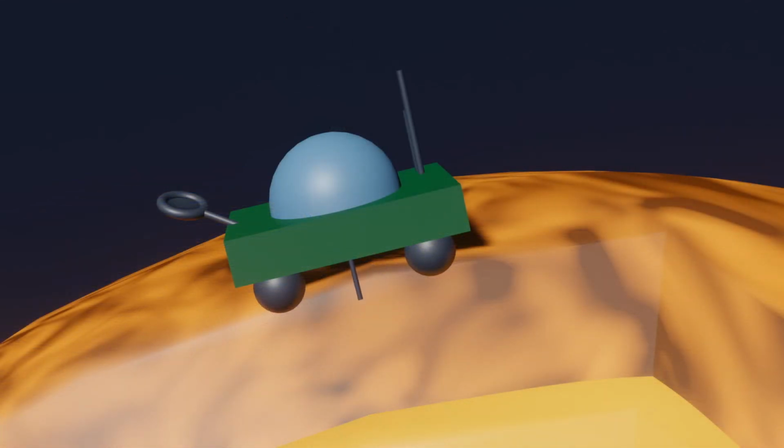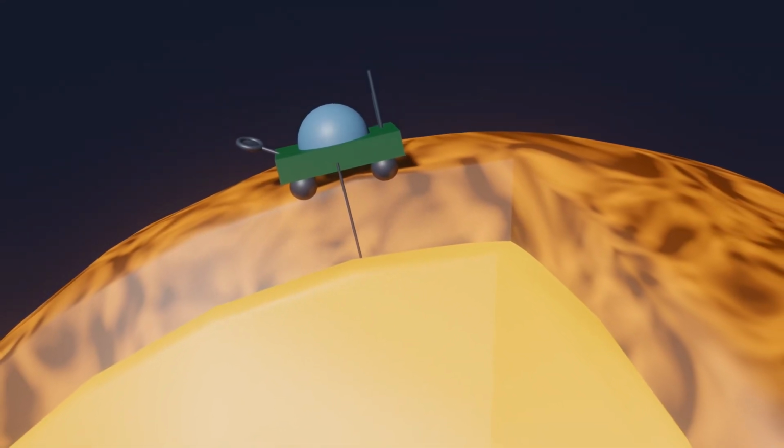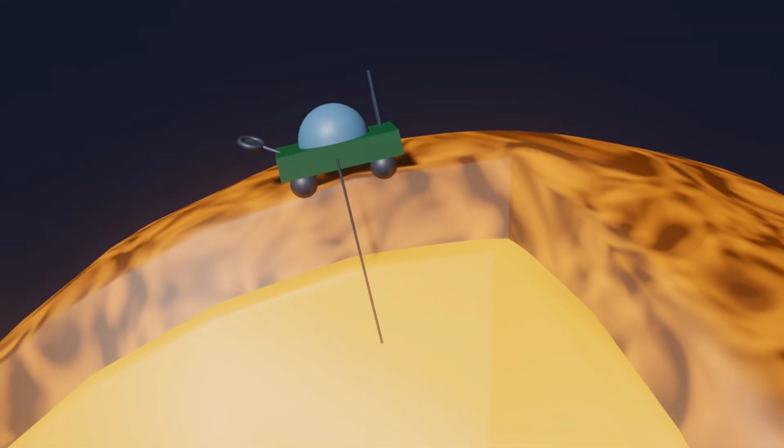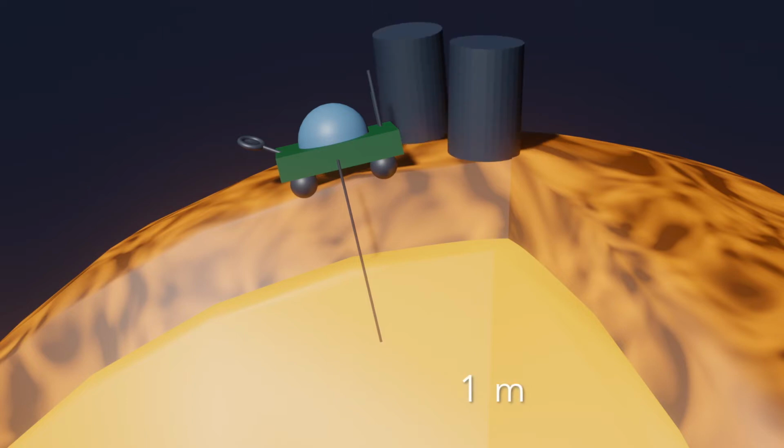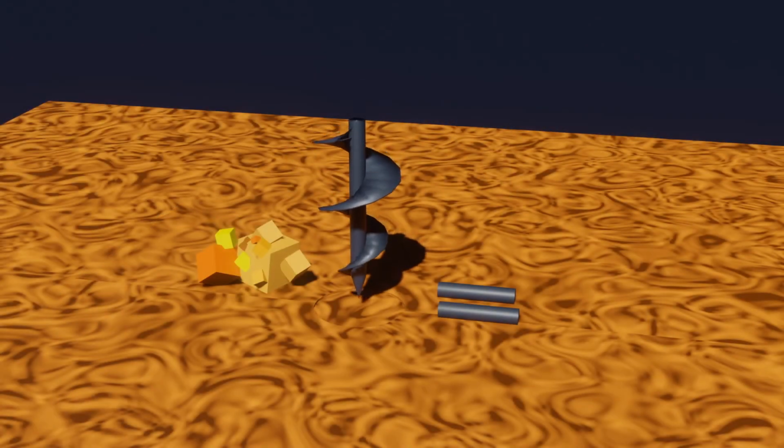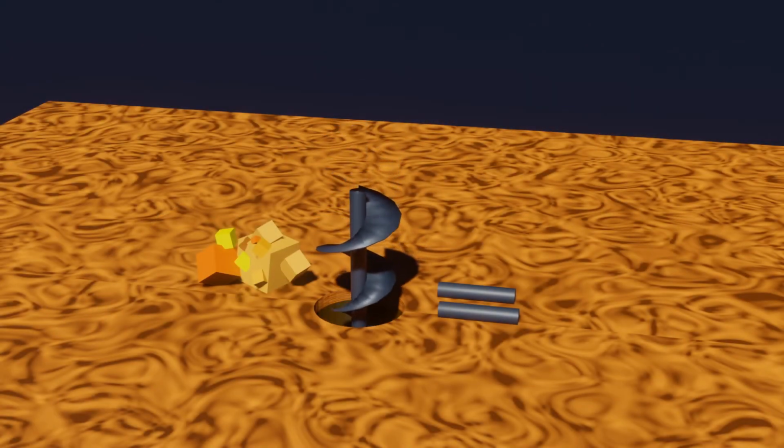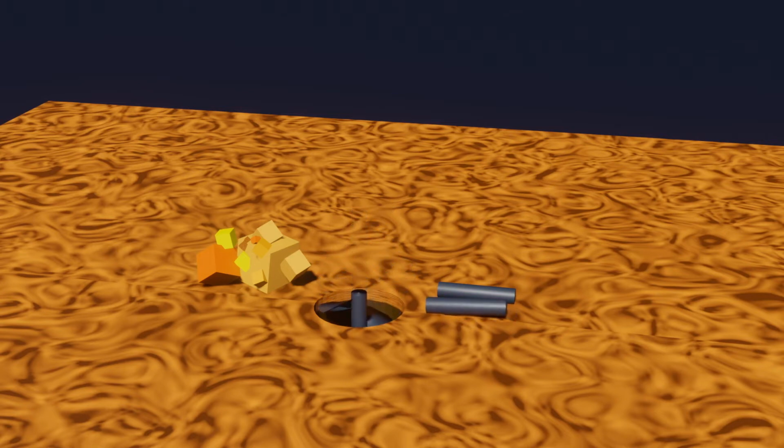A disadvantage of rotary drilling in general emerges regarding the drilling depth. For depths deeper than about 1 meter, it becomes challenging to provide a fitting infrastructure for the drill. For deeper depths than about 1 meter, it will be necessary to autonomously assemble the drill string in the extraterrestrial setting. It is possible to assemble the drill string while the drilling is in progress. As the drill advances deeper into the body, individual drill segments are attached to the continuous drill pipe.